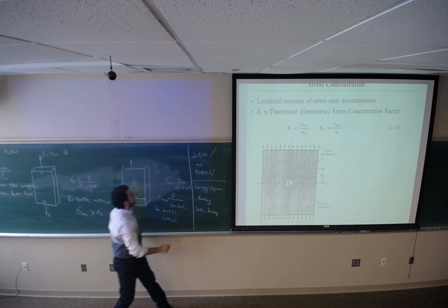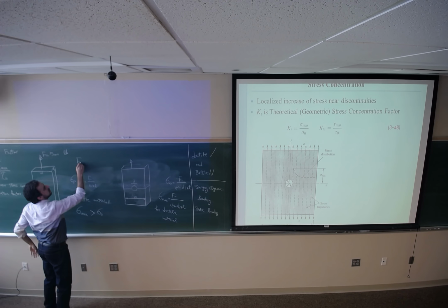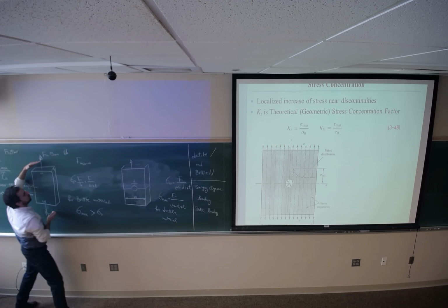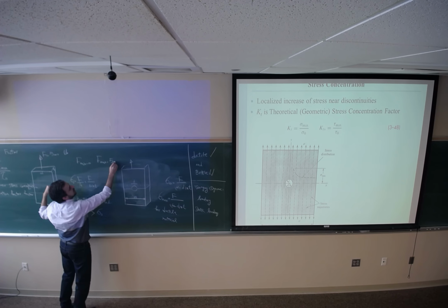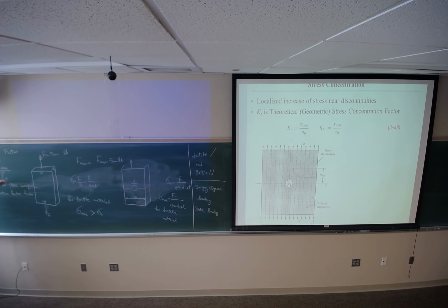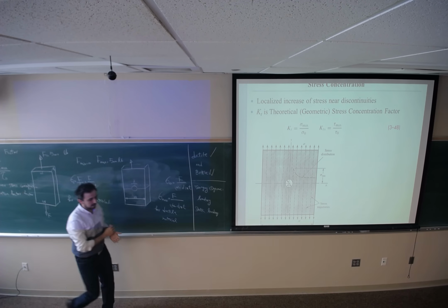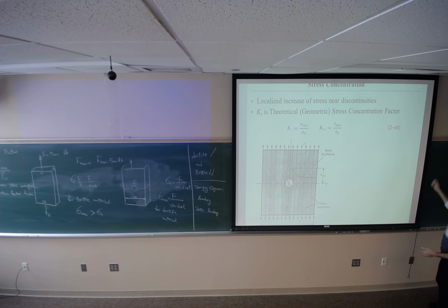But if I push 500 pounds and then release that, then again I push 500 pounds, then release that, F mean is going to be 0, no force. F max is going to be 500. So we are saying that we have varying loading, or dynamic loading, because the load is varying over time. So it makes another problem, which is fatigue. We will cover that in chapter 6.